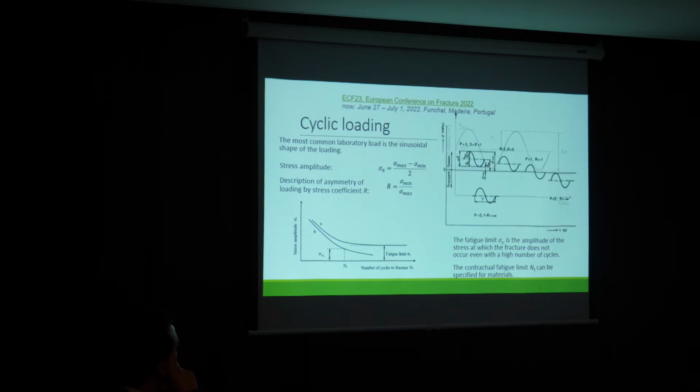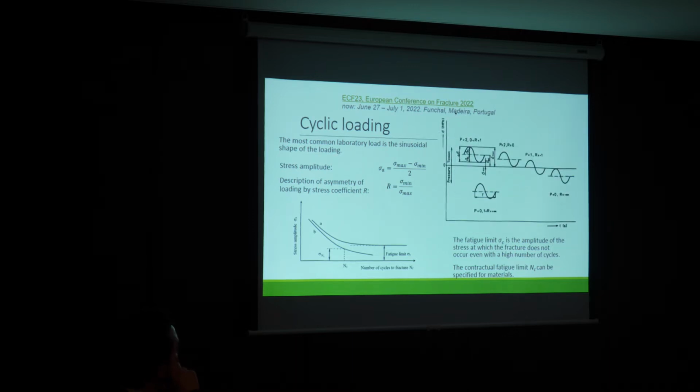You can see here, as I discussed before, the stress ratio. The typical value for a rotating part of an engine is -1. Then R in compression is this part, and some elements could be loaded by R 0, but in our case it's 0.1 because we suppose the load from the overweight, and we added some load from a car or train or similar.